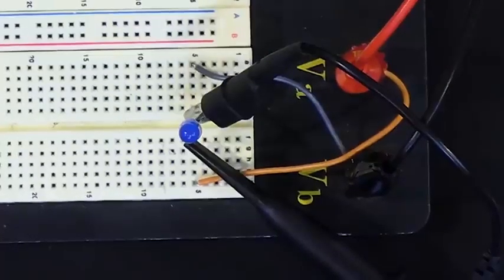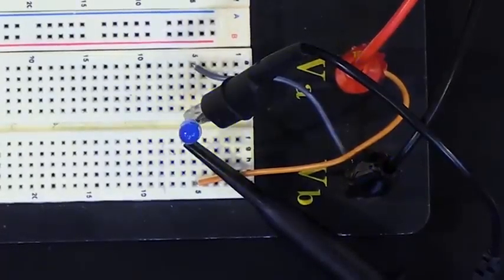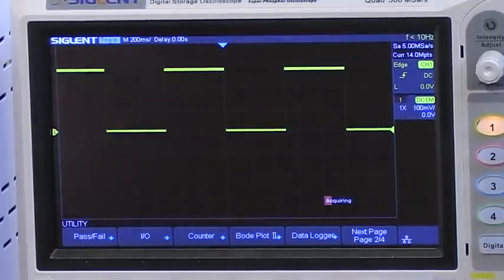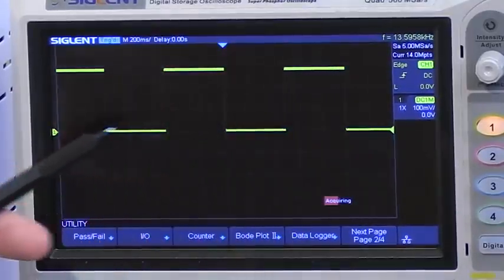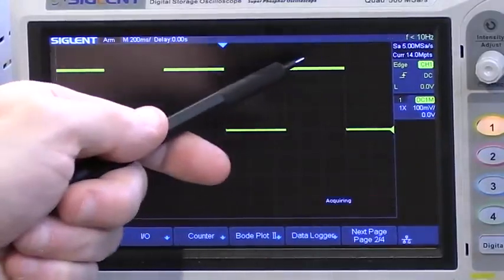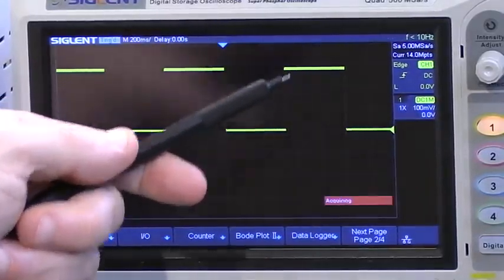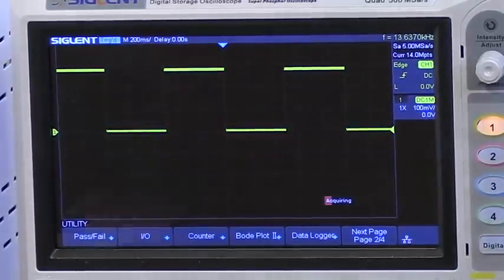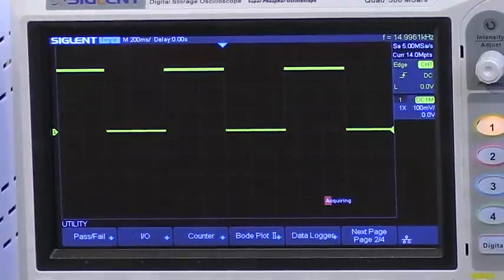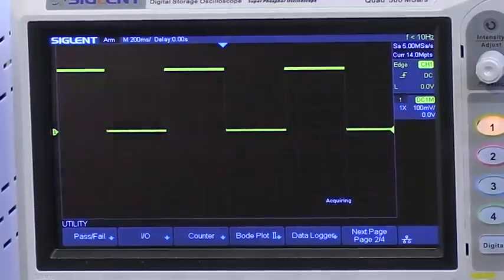We turn the output on and we see that this thing is now blinking, right? And we look on the top display and this oscilloscope is showing the voltage across this diode in real time. So this right here is the 0 point, 0 volts. The top little hats up here are, I think I set it to 2 or 3 volts. Actually, I can read down here. It says 3 volts. So I'm driving at 3 volts, and then 0, and then up and then down, and then up and then down there. So it's turning on, off, on, off.